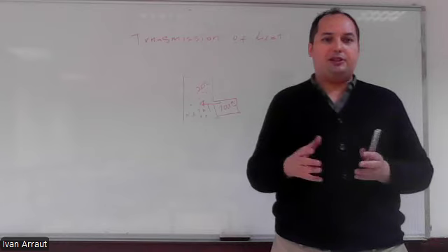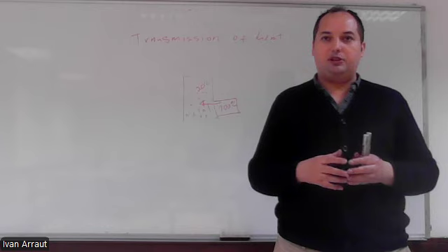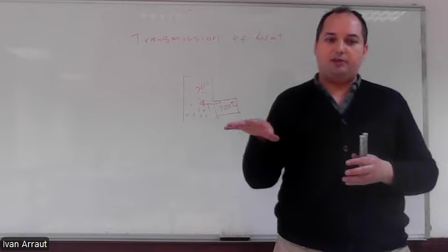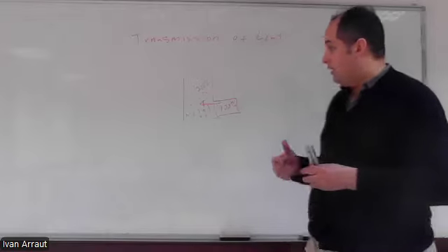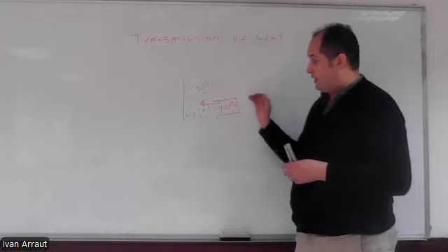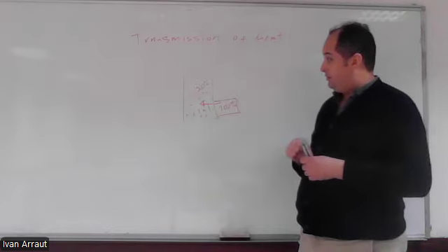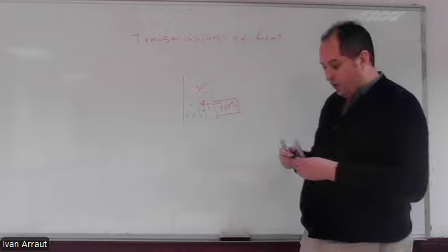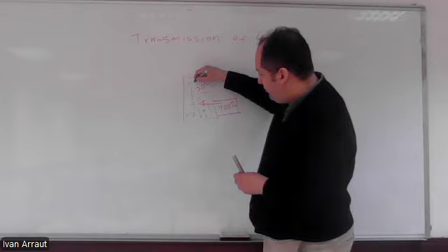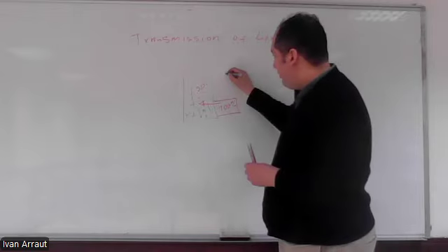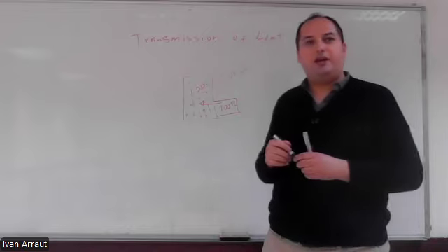But for example, if you put a ceramic, the electrons are not free, so the ceramic doesn't transmit the heat so easily, because it transmits it via other degrees of freedom, which are vibrations of the molecules and so on. In this case, the heat flows from here to here, and then the charges, the electrons or vibrations, start to move. This is what we call transmission of heat via conduction.